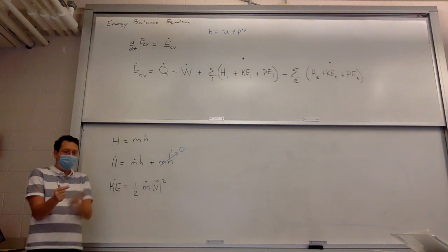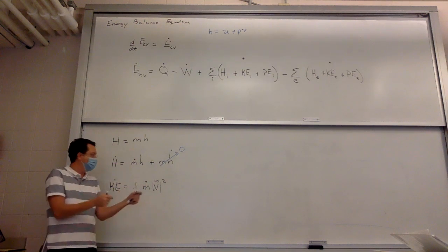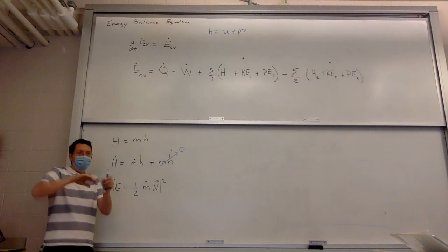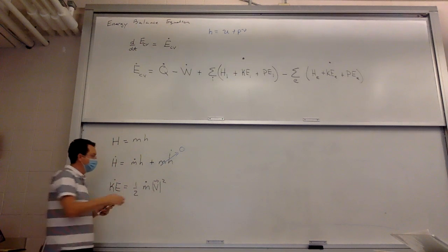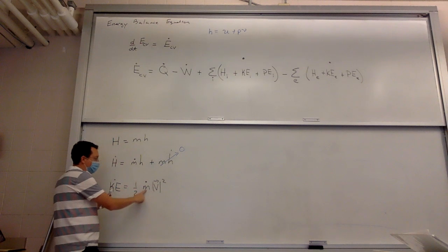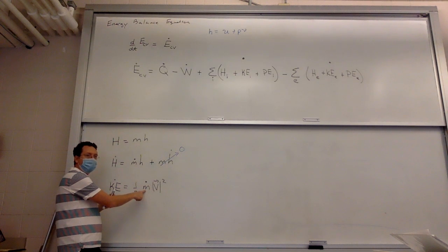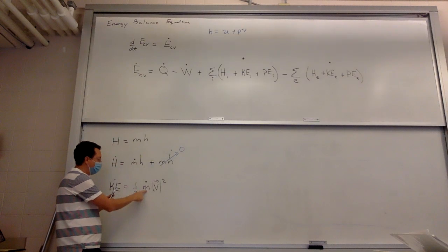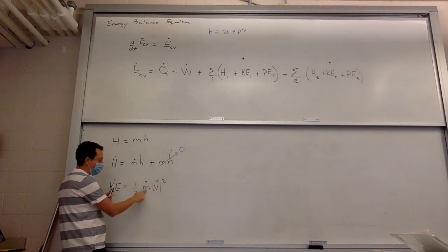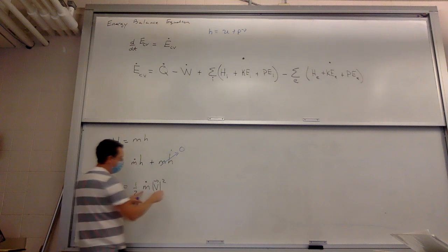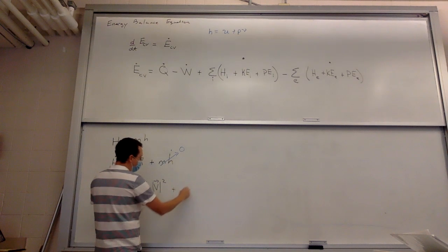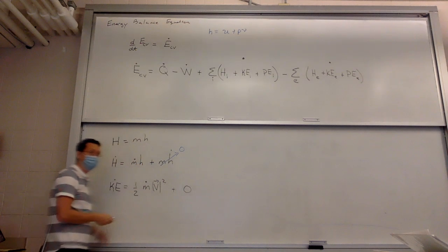One droplet pretty much has the same velocity as the one right next to it. And furthermore, it's more or less constant. Like it's not changing in time. All of the time dependence just comes from jamming in more or less droplets per unit time. So we're saying all of the time derivative here is basically carried by the mass flow rate. Plus, you have another term, but we're going to say that one doesn't contribute.